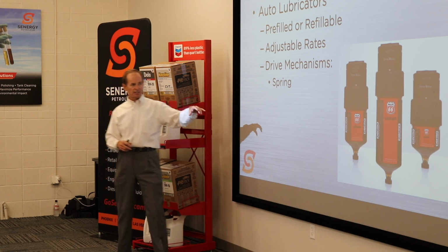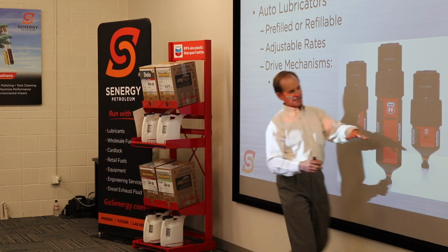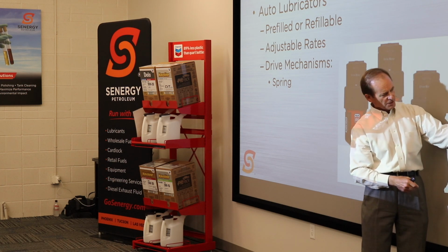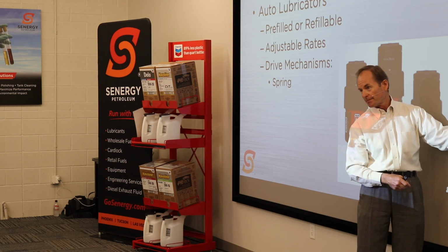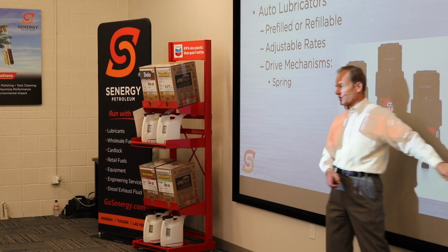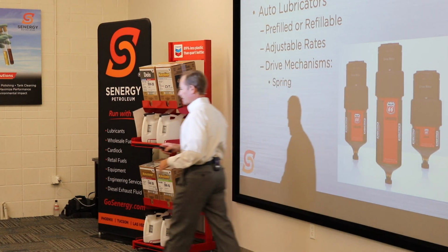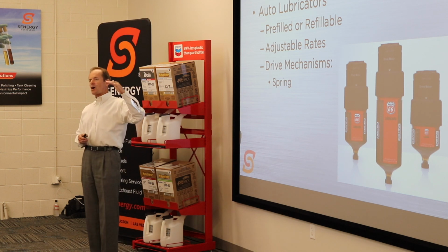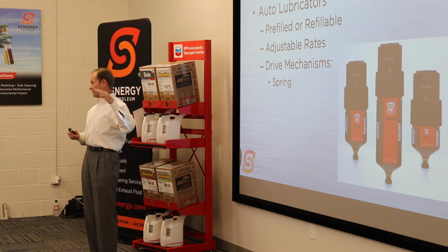If you've ever seen these, it's as simple as a plate with a spring going up here. So you pump your grease in, and it starts pushing it out. And you govern the size of the opening to tell you how much grease you're going to get out. The biggest disadvantage of the spring-loaded ones is that spring always has pressure on that grease.